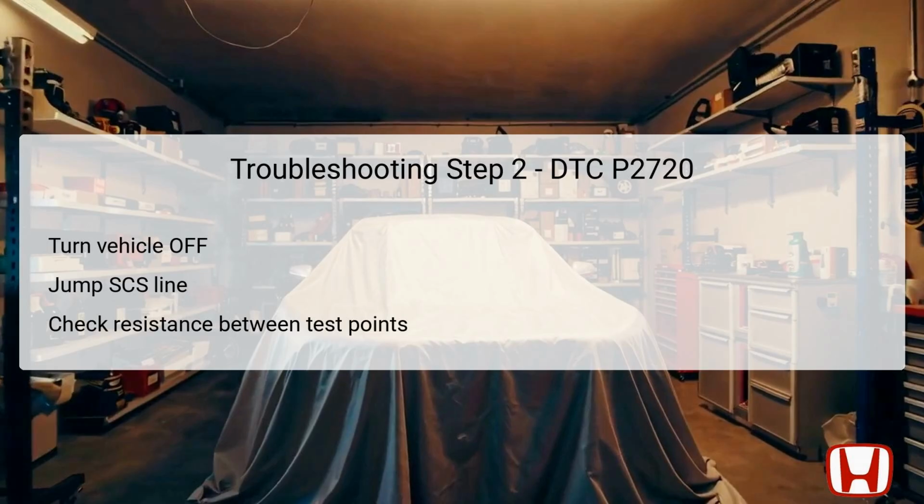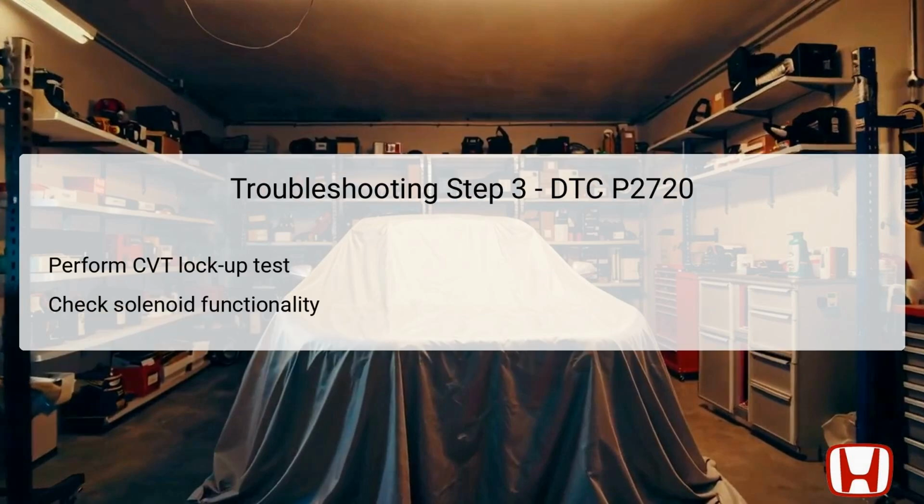If not, investigate and address potential issues with the number C35 fuse or any open circuits in the wire between the powertrain control module and the under-dash fuse relay box. At this stage, the troubleshooting involves assessing the functionality of the CVT lockup clutch control solenoid valve. This component is crucial for the vehicle's transmission efficiency and response during various driving conditions.